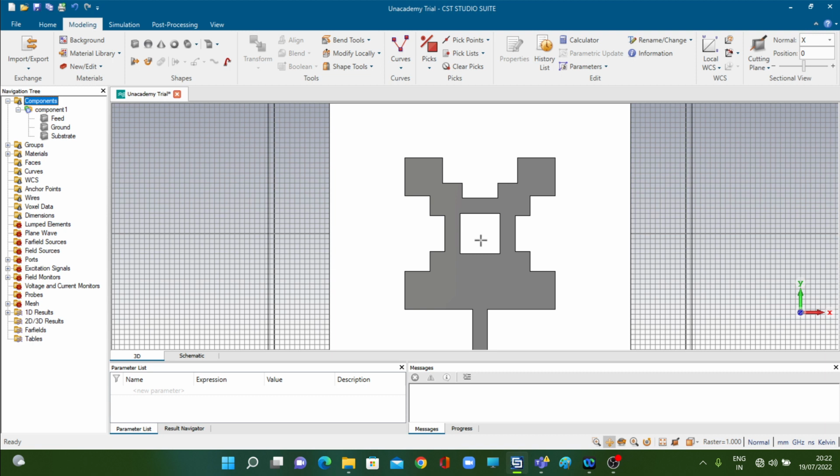And at the same time, see, whenever there is metal, we have actually learnt it previously, there are always conduction losses involved. Because current flowing through metals dissipates energy according to Ohm's law, according to the resistance of that metallic conductor. And so there is conduction loss. In terms of antenna design and performance, this conduction loss can severely limit the bandwidth of the antenna.